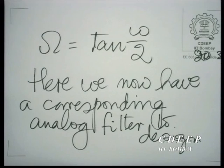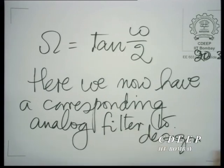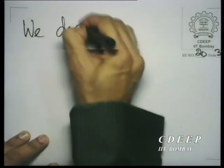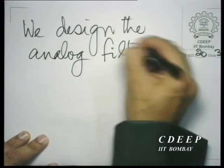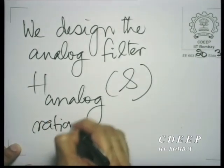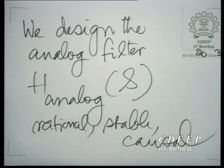So, what would you do next? Of course, you would design that analog filter, take advantage of the known methods for analog filter design and design that analog filter. So, we will assume we design that analog filter. Let us call it H analog, and that would be a function of S. It is a rational function of S, rational, stable, causal. There are several different approaches, and we will look at some of them. In fact, we will begin by looking at the low pass filter design.